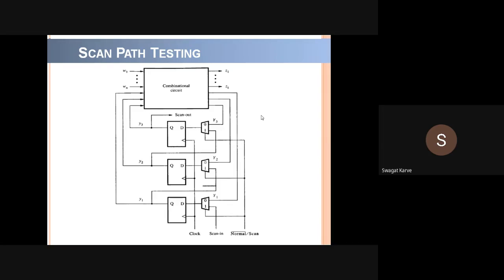and you can simply go for the scanning of that circuit by using those steps: enable scan mode, then enable scanning data, then disable scan mode, enable the clock pin, then again enable scan mode and observe the scan out, right? Your job is only to enable and disable, give the clock, and observe the data, right? Test vector generation will be taken care of by the ATPG program, that is automatic test pattern generation. Clear? So these are the advantages of this scan path.